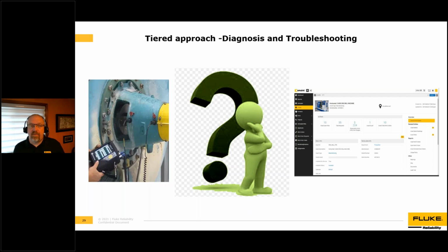So, armed with the recommendations of remote condition monitoring and wireless screening tools, the on-site vibration analysts take hand data of equipment with advanced vibration data collectors. These on-site personnel observe the equipment, review the data, and verify the failure state. They then make the recommendations for repair or work requests into your CMMS, or computerized maintenance management system. Some of these online and remote condition monitoring systems report directly to your CMMS. Since this equipment has been pre-screened and already shows some evidence of potential faults, your site vibration analysts are able to focus on other aspects of condition monitoring.